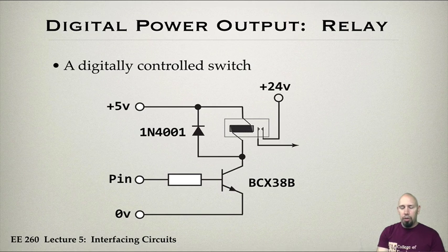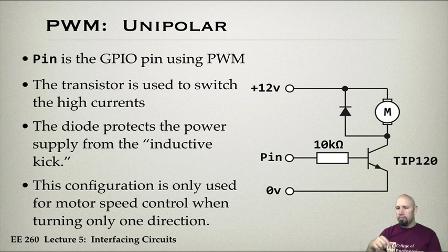For example, it may require so much that we would use a relay to drive yet another relay in order to do what we need to do. We saw how we used one switch to control this switch, which controls something else. We could use this switch to control even another switch to control something else, and so forth. If you don't have it available with what you have, then you build up from there. So this is the basic digital output for power. This can allow the control of large power, which can be very important.